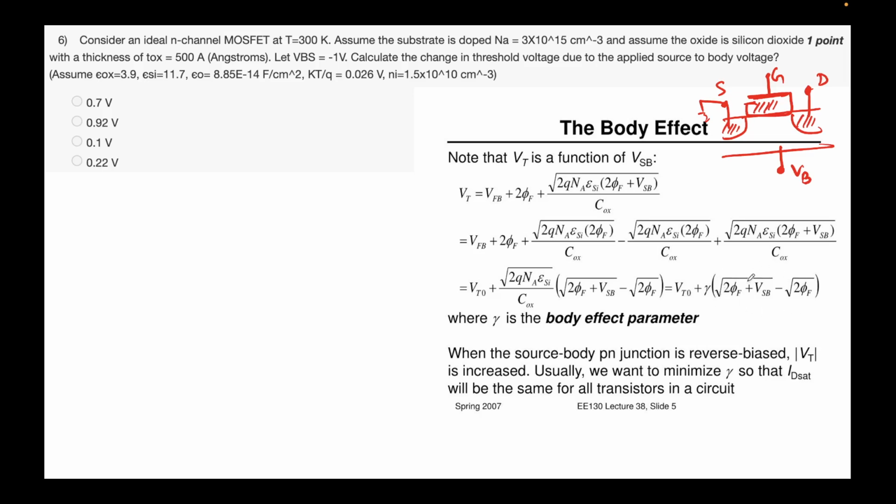So once you have fabricated the device, you cannot change the length and doping, but what you can change is Vg, Vd and also Vb. So Vb is also a good control because now you can change the threshold voltage. Okay, so sometimes you do it deliberately.